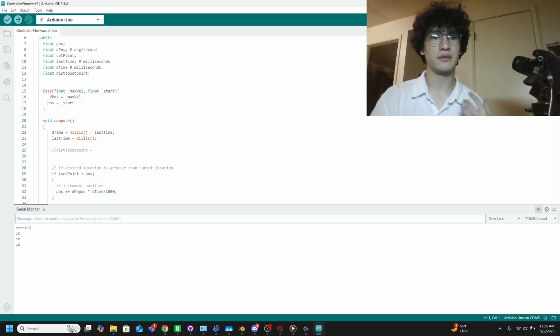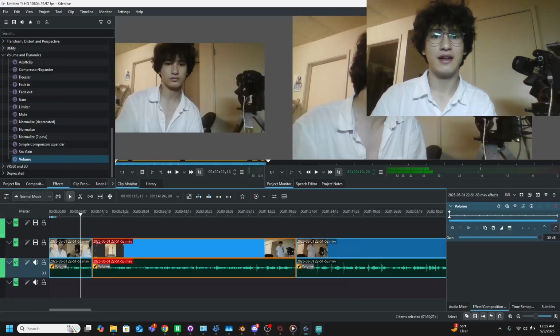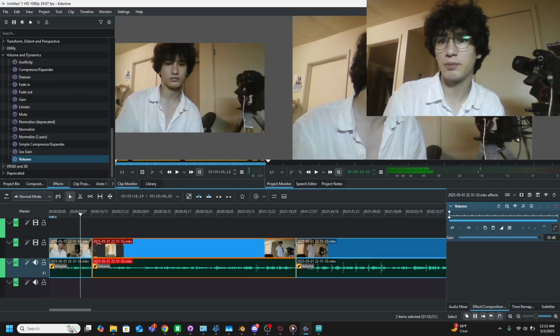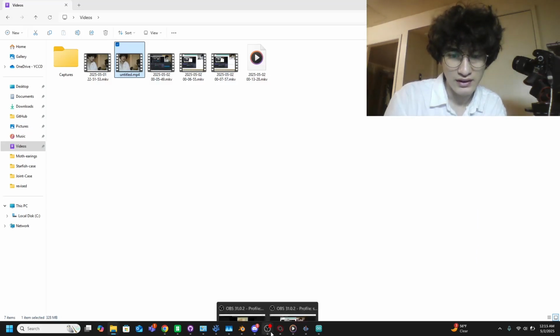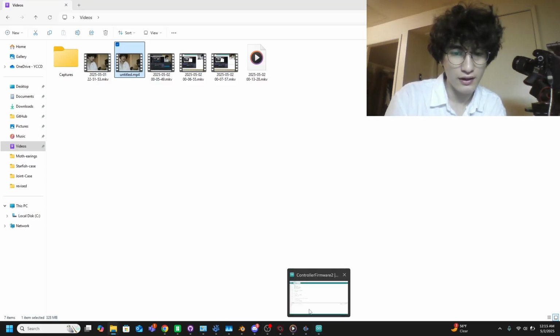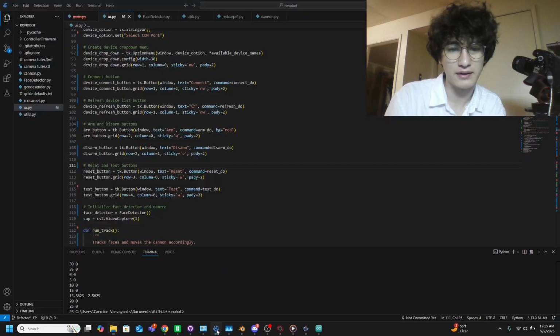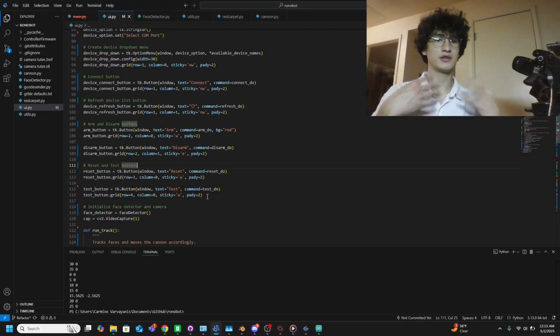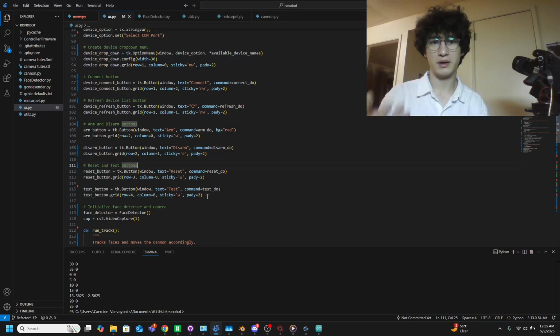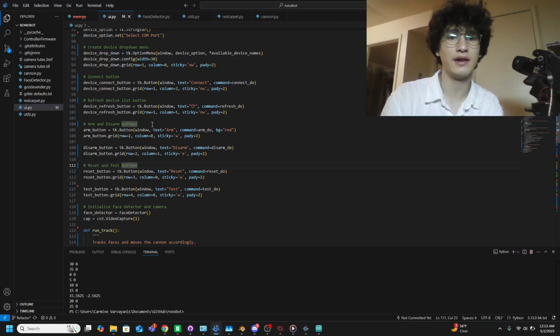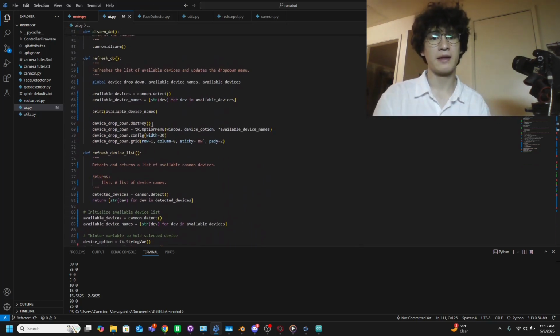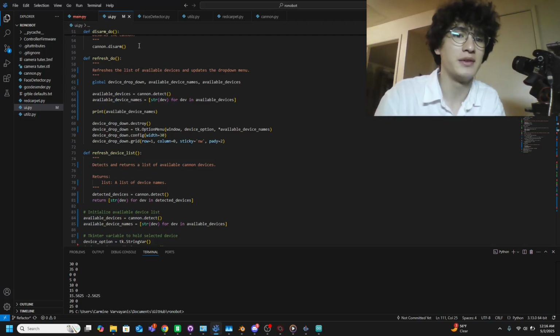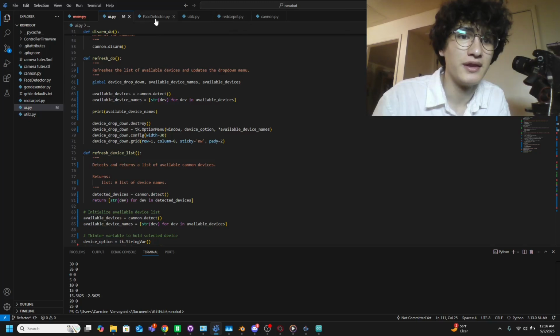And something that was really tripping me up is that it expects a special line ending when you send the commands, right? Because you can just send a stream of bytes over serial, but it needs to have a line ending at the end of it, so it knows where the difference is. But different protocols and different standards and different machines expect different line endings. And I had trouble figuring out exactly which one I needed to use.